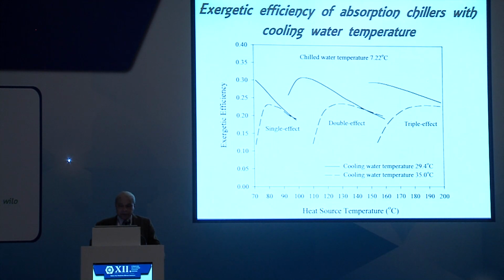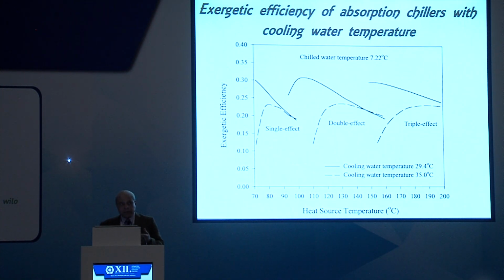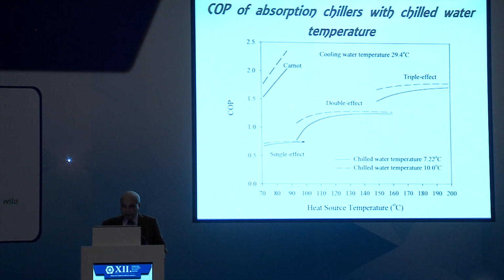And this is the exergetic efficiency for those of you who are into exergy, such as my professor, my dear friend Professor Kilkish, who would probably be more appreciative of that, because I believe, and many of that community believe, that eventually over time we will be paying not for the cost of energy, but we will be paying for the cost of available energy. I think over time that is going to be the trend, as opposed to the cost of energy. So exergy becomes an important issue to deal with. And that's what the people that do thermoeconomics will tell you.